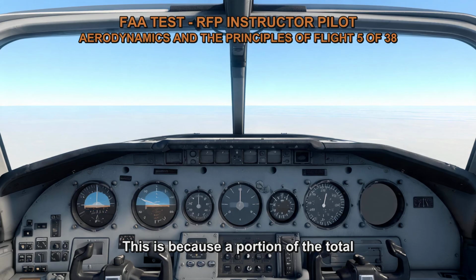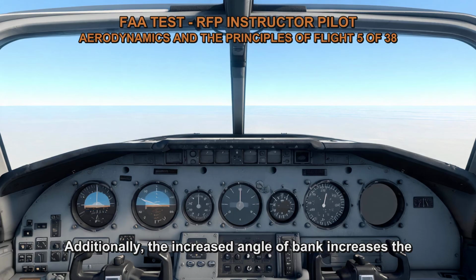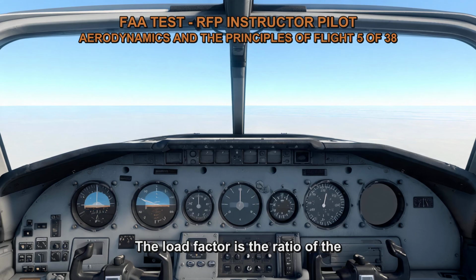This is because a portion of the total lift is now acting in the horizontal direction to provide the centripetal force. Since the vertical component of lift is reduced, the opposing force to gravity is also reduced, causing the aircraft to descend or sink. Additionally, the increased angle of bank increases the load factor on the aircraft. The load factor is the ratio of the lift to the weight of the aircraft.